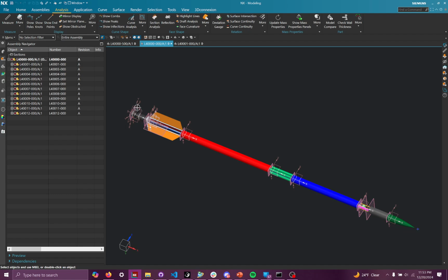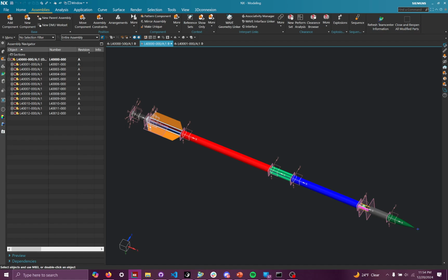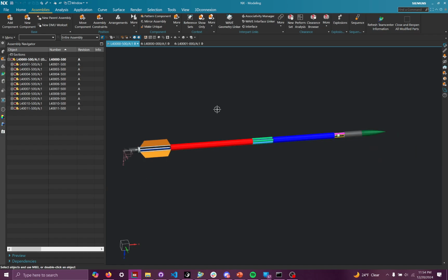But anyway, yeah, you can change the vehicle length and different subsystem lengths within this vehicle layout file, and that change will be propagated down if you do that process of either loading in all the layout files or doing the load interpart data thing. So that's one part of it. That's the vehicle layout and assembly files.